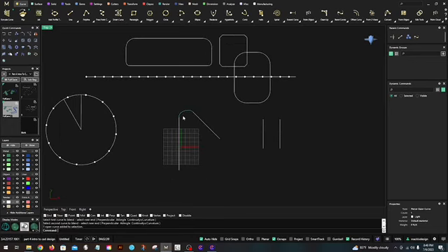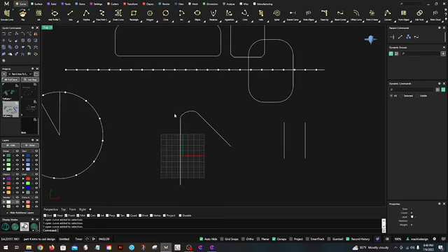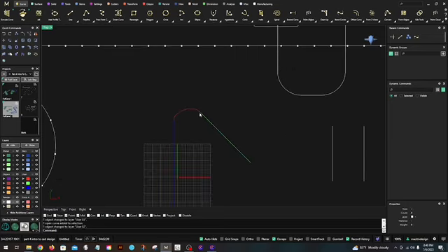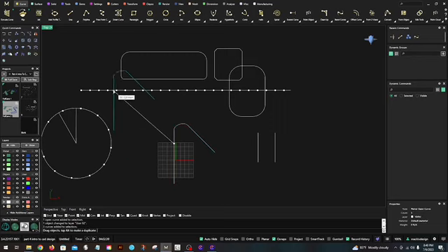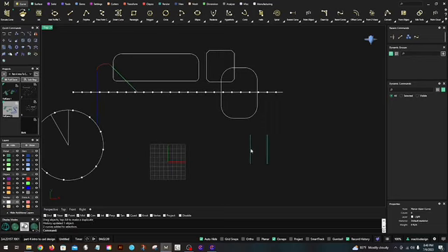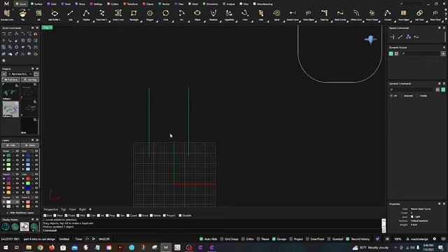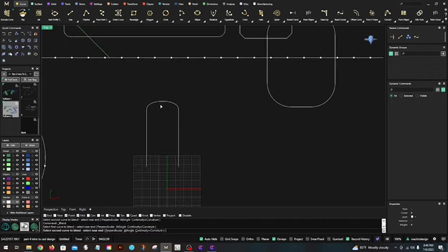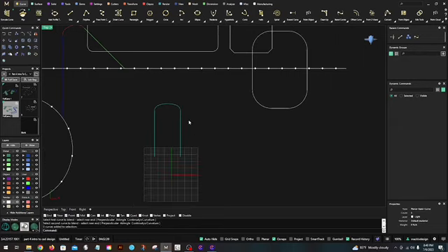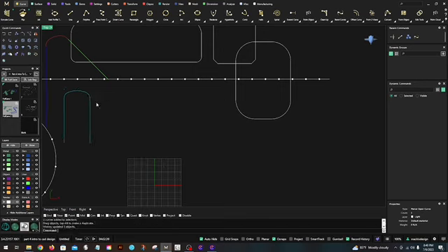And that does not give you a join. So those curves are still separate. Okay. I'll just put this over here and bring these over. And let's try that again. Blend curve. I hit this first curve, then the second curve, and it blends it. There's really no adjusting, no choice in how that blends. It just picks a nice smooth blend.